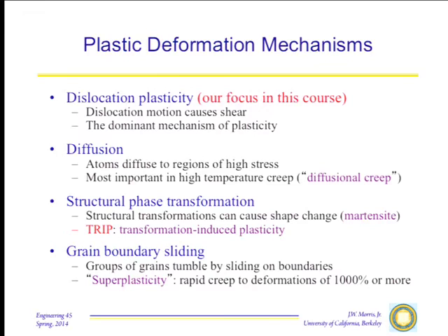For example, by diffusion. If you take any material and just let it sit around under load, the atoms will reconfigure themselves over time to adjust to that load. There will be what we call creep, diffusional creep, goes on in any material at any time because of the motion of atoms in response to the applied stress.